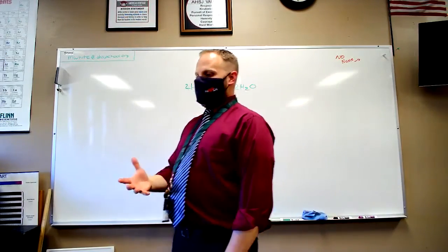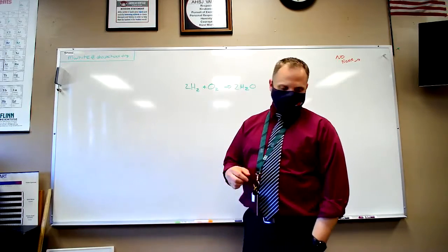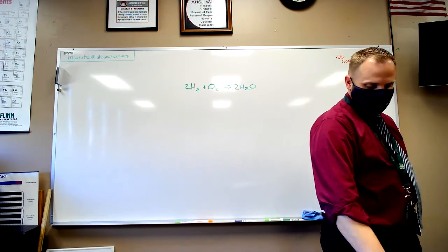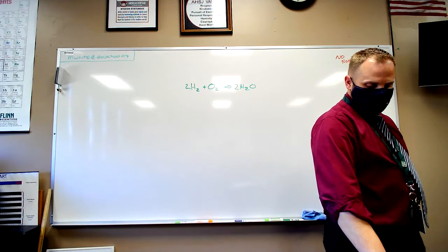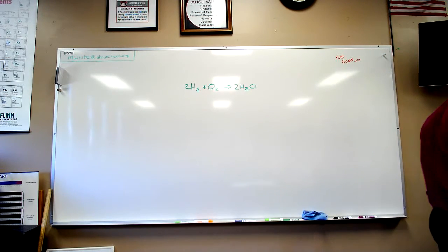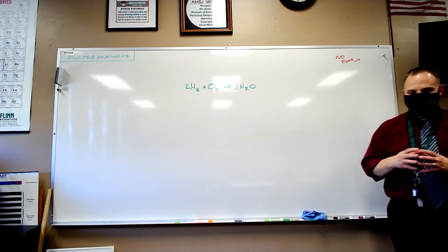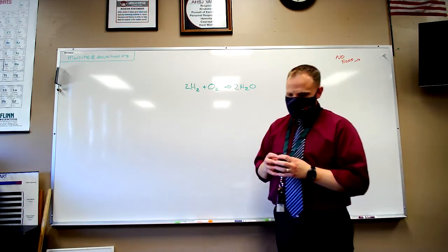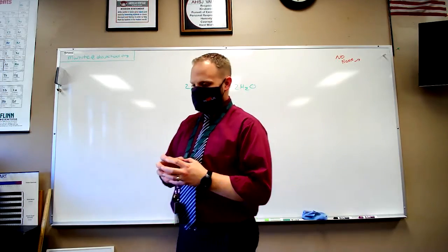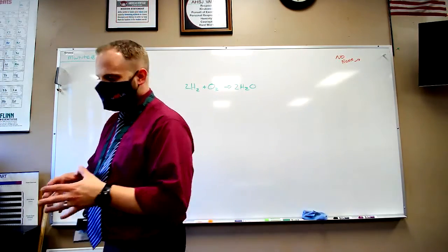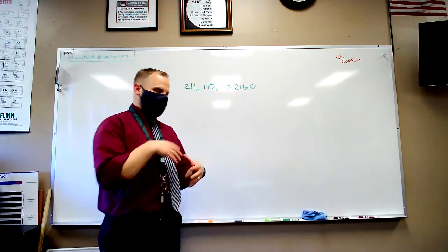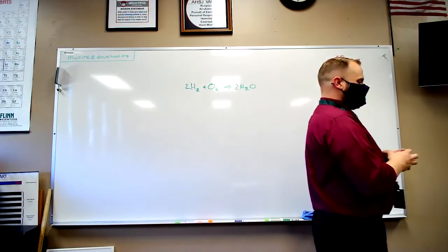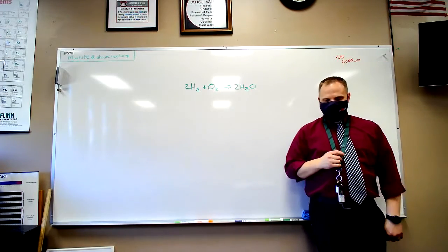That is a redox reaction. It is also what we call corrosion. The iron is reacting with things in the environment to create iron oxide, so you no longer have iron. Iron oxide is rust, it flakes off, and it weakens the structure of whatever it is you had.